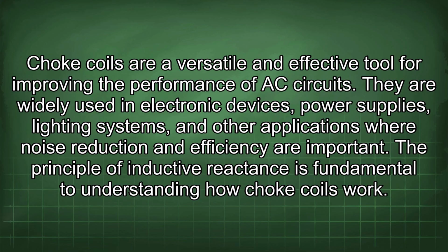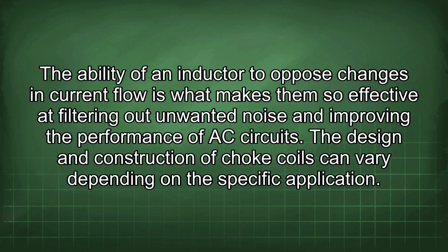They are widely used in electronic devices, power supplies, lighting systems, and other applications where noise reduction and efficiency are important. The principle of inductive reactance is fundamental to understanding how choke coils work. The ability of an inductor to oppose changes in current flow is what makes them so effective at filtering out unwanted noise and improving the performance of AC circuits.